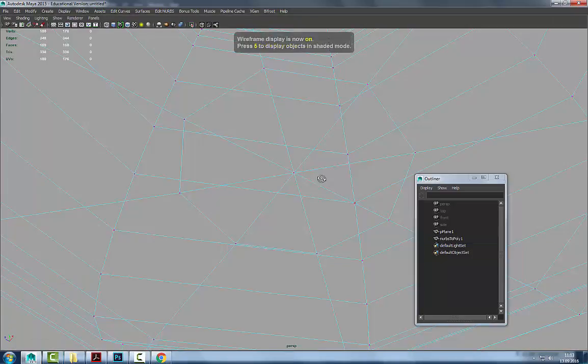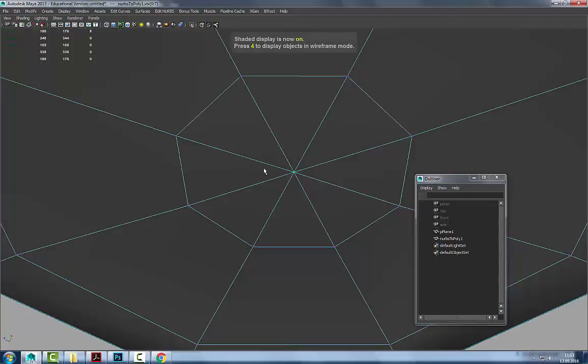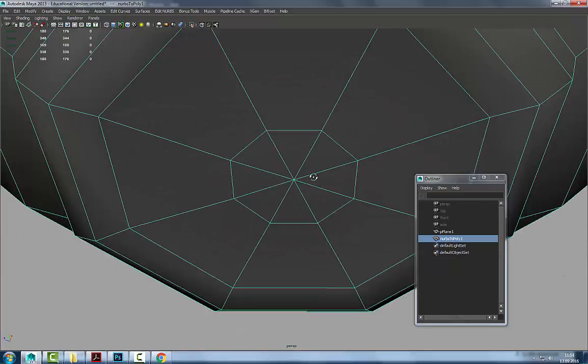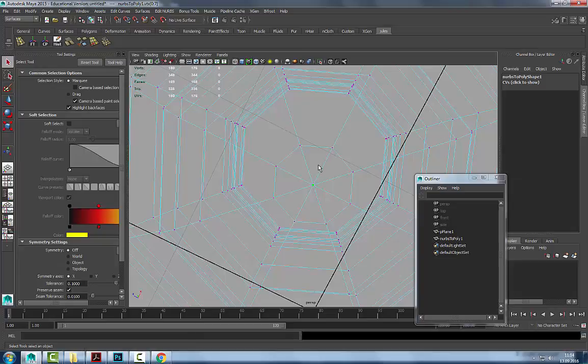No, there are 8 vertices, because we have 8 incoming edges for that middle point. You can't really see it even when I subdivide, because they're just meeting in that one point. This is something you would just have to know. But the middle point, I would just merge to have a nice mesh.